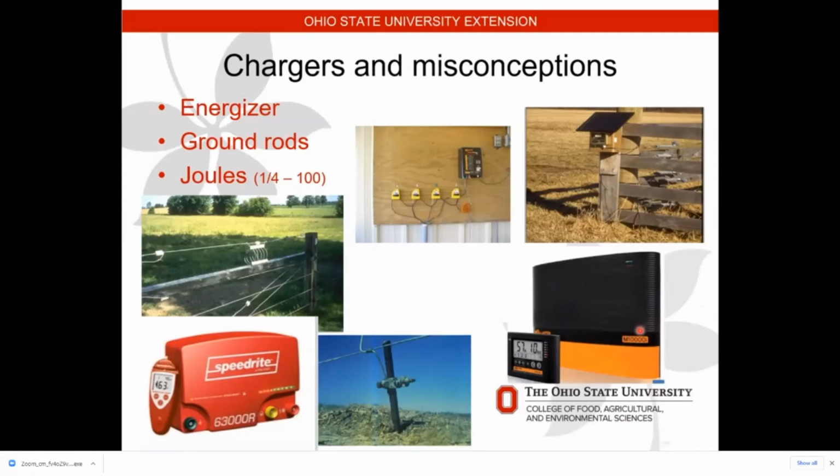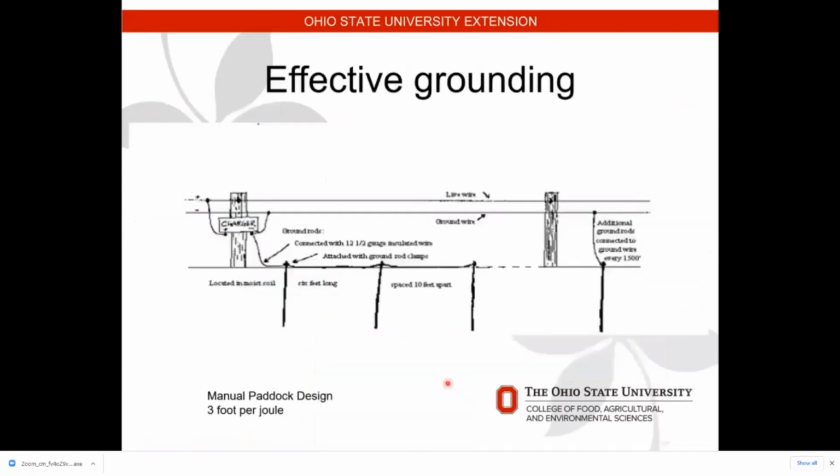A charger like this may take 10 ground rods, and that's our next section. Probably along with chargers, another big mistake that I've made and others is we don't ground our chargers enough.